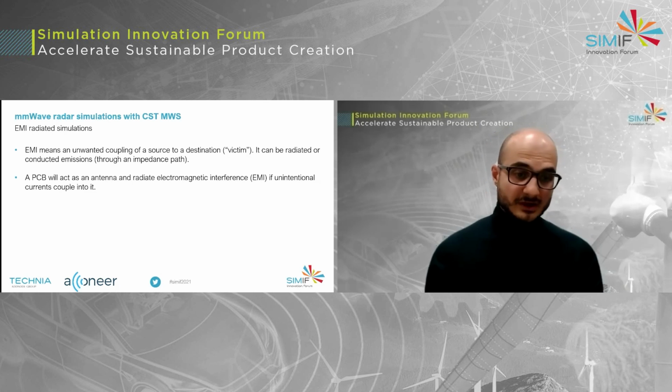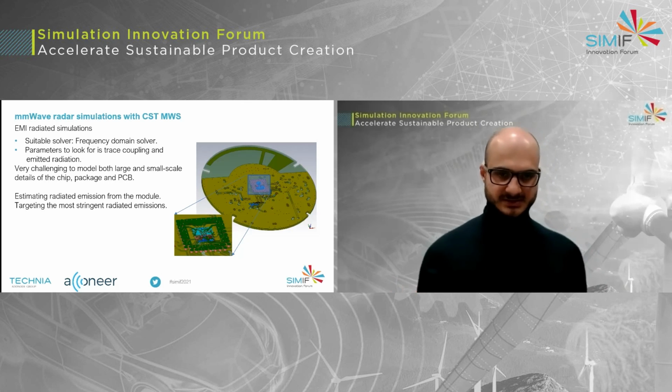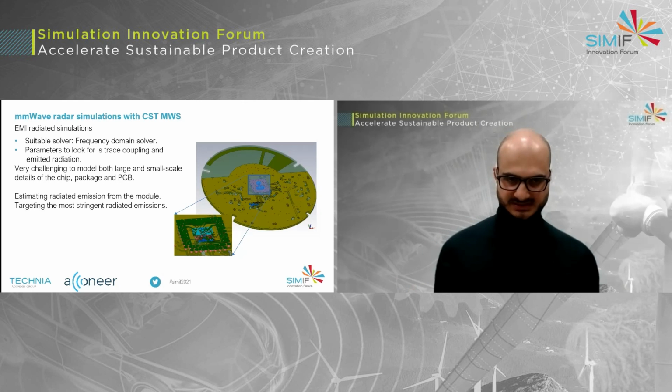For this, it's quite important to have a very detailed model of the product. In this case, we need to model the interface between the chip package and the PCB, and this involves large and small scale details of the chip package and PCB. To do that, we found the suitable solver to be the frequency domain solver, which is suitable for this type of investigation.